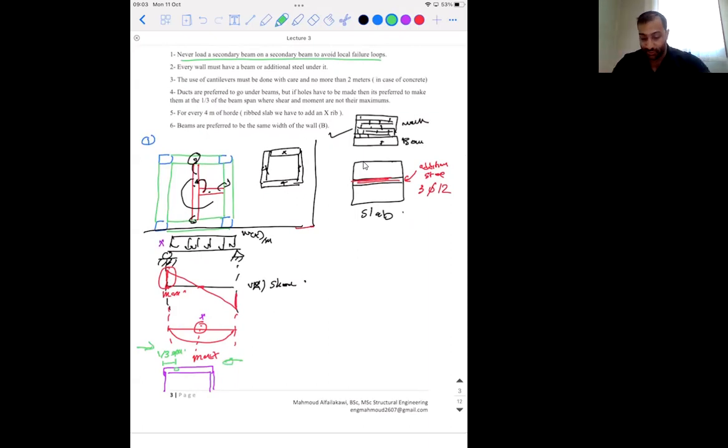At 1/3 of the span, because you have maximum moment in the middle, so you don't want to reduce your section by cutting a hole, and you don't want to cut at the beginning, so you don't reduce the shear resistance. Unless you calculate and mitigate, if you want to break these rules, you have to mitigate. It's possible. I'm not saying it's not. I've seen it happen, but you have to be careful.